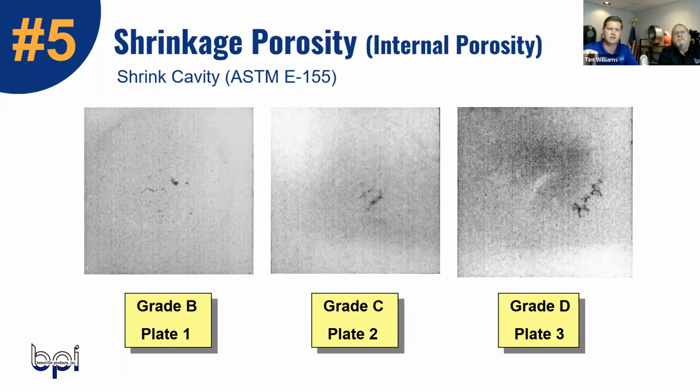Is the shrink cavity more specific than what you'd see in the elongated side of things? On the elongated, it looked like there were a bunch of those little porosity holes or shrinkage holes versus what you're seeing here in the shrink. It's a progression as you start to feed through the risers, depending on how well you did it. Like you said, the elongated shrinkage is your first near miss. Then it goes to the sponge shrinkage, which means you missed your feeding range by just a little bit more. And then the one where you just don't quite have it yet goes to a shrinkage cavity.